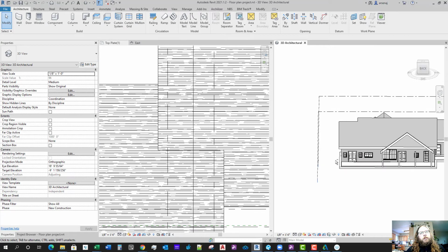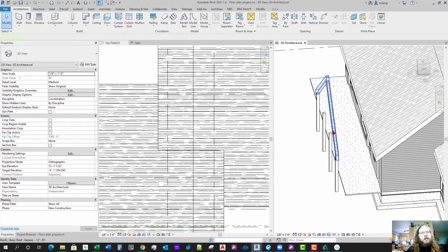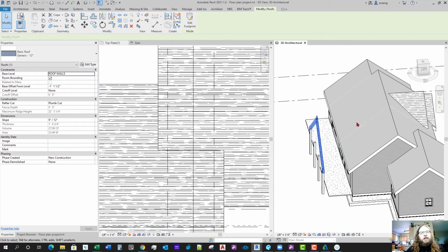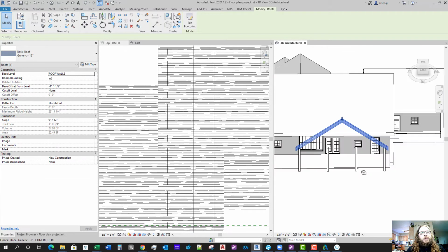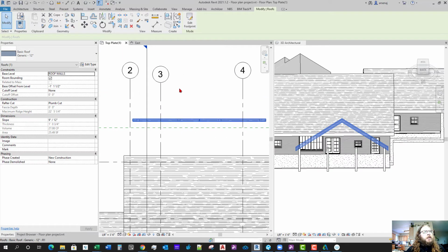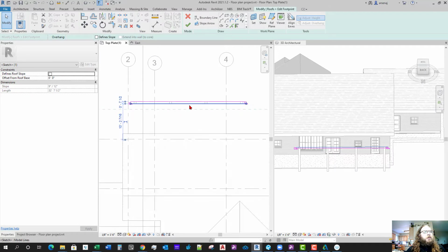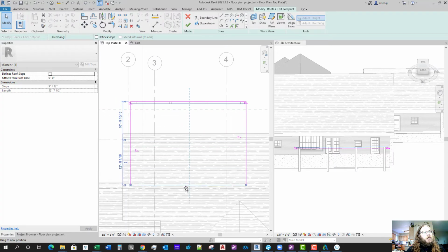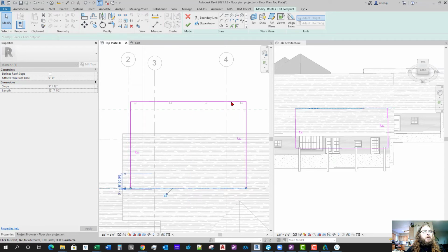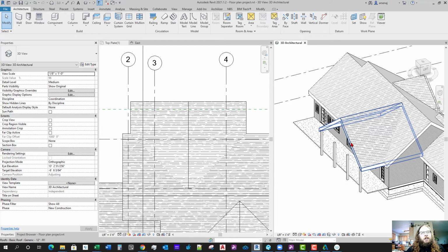And it looks like we're getting pretty close, and the last thing we'll need to do is bring this roof back to this wall here, or to the roof there. So let's go to the plan view, and we'll edit this boundary, or edit footprint. Drag this boundary line back, just so it's over the roof.